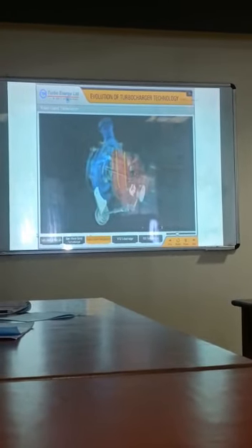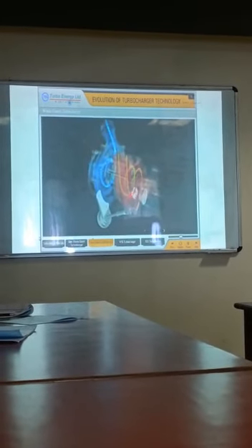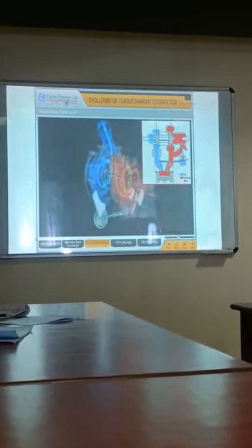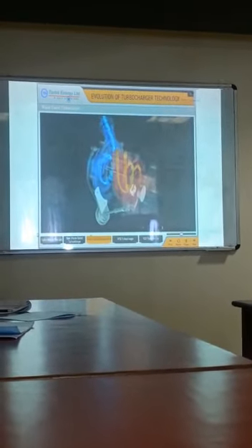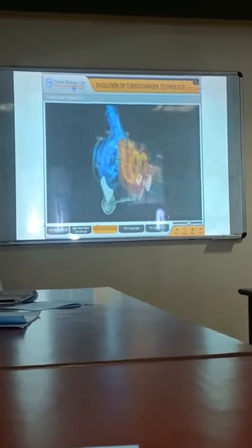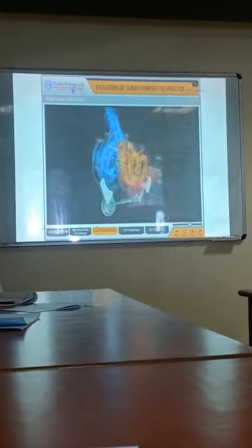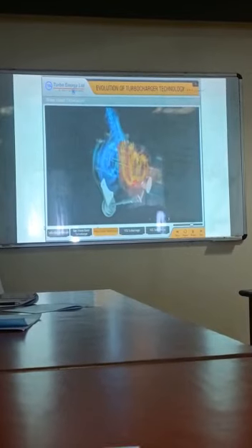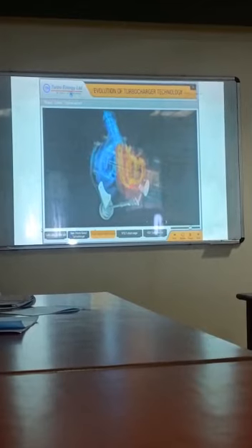In a normal working condition, the spring-loaded diaphragm keeps the wastegate flap in closed condition. When the air pressure in the compressor exceeds the diaphragm spring pressure, the spring gets compressed, the diaphragm moves and opens the wastegate flap assembly fitted in the turbine housing assembly, thereby allowing some amount of the exhaust gases to bypass the turbine wheel and exit through the turbine housing outlet.